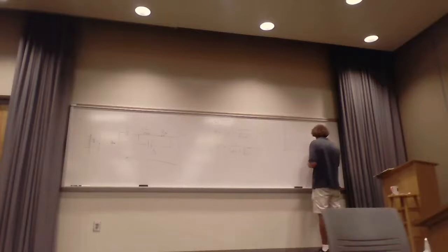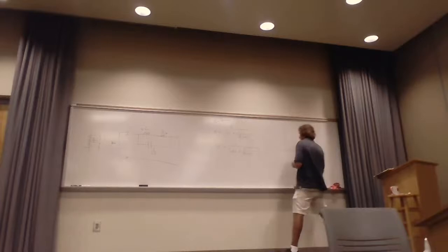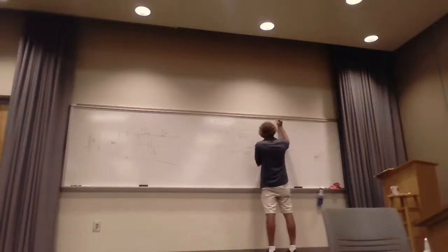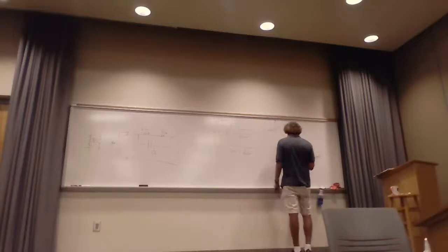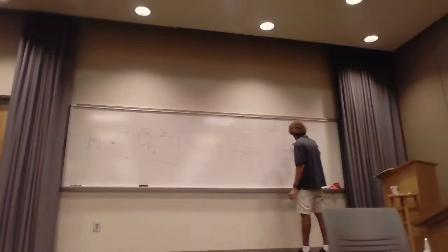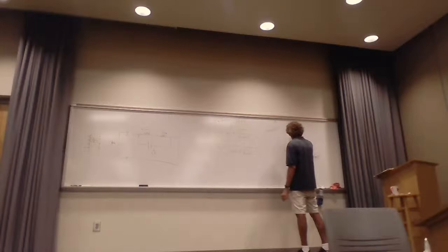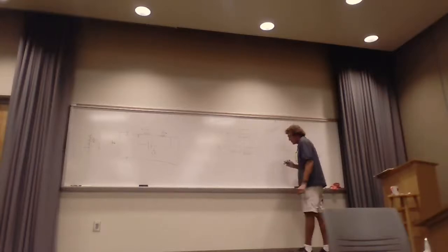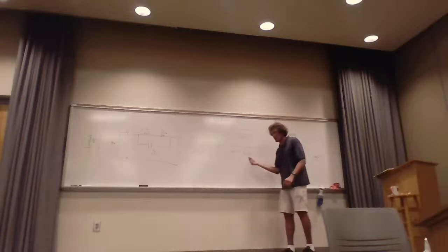If this is the plot, the log of F here, and on this axis, plot 20 times the log of the impedance Z, here's what actually happens. At very low frequencies, this thing's coming in at 20 dB per decade. And I'll spend more time with why it is 20 dB looking at these equations.